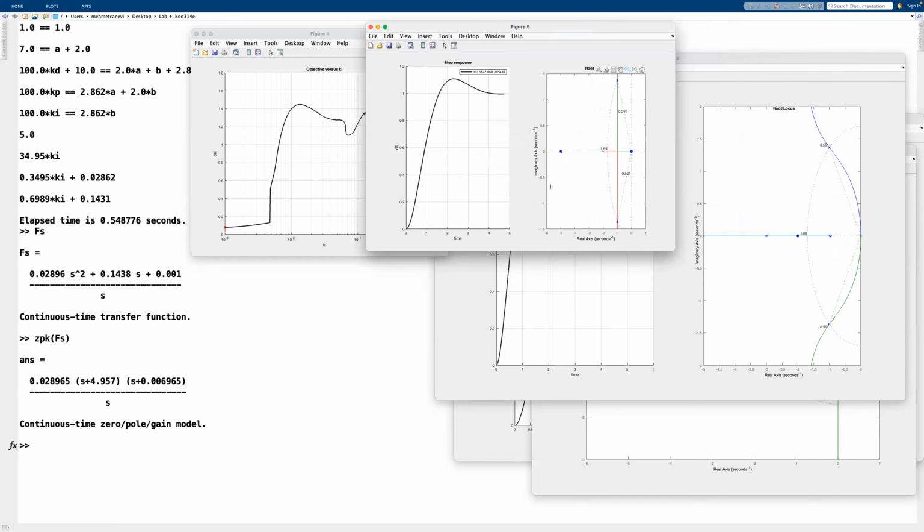Of course, there's a difference between canceling poles and zeros in closed loop and in open loop, because this is a closed loop cancellation. This happens in the closed loop. So if it's near, then we are also okay because it will be a pole zero pair. And if it's out of the dominant region, that wouldn't affect the system that much. But if it's in the dominant region, it will probably mess up the system's behavior. And other than that, it might be even worse if it's an open loop control, because we're not measuring anything. So yeah.